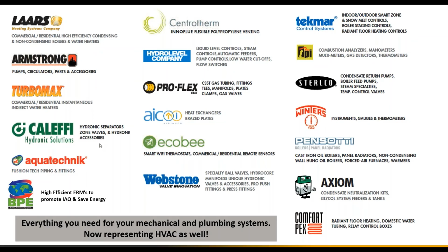Especially with cast iron radiation, even baseboard, ideally you could run the system on continuous circulation, with the water temperature in line with the outdoor temperature conditions. Instead of an on-off system, you have a continuous operating system.